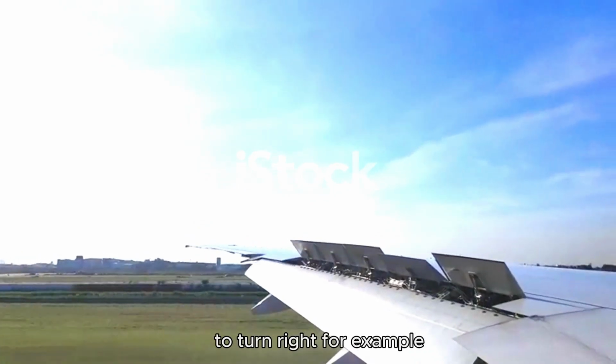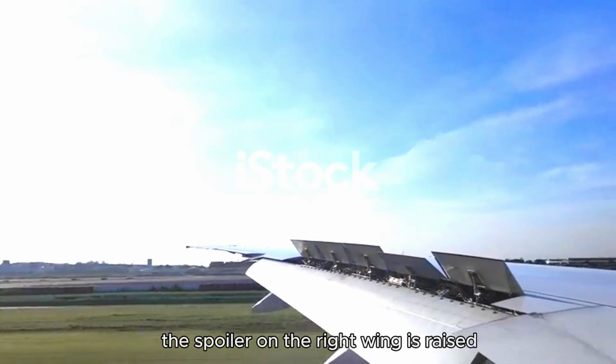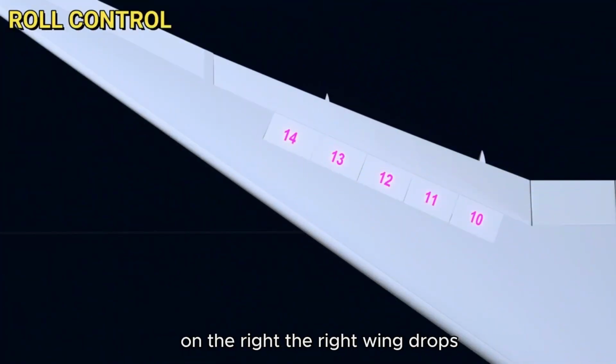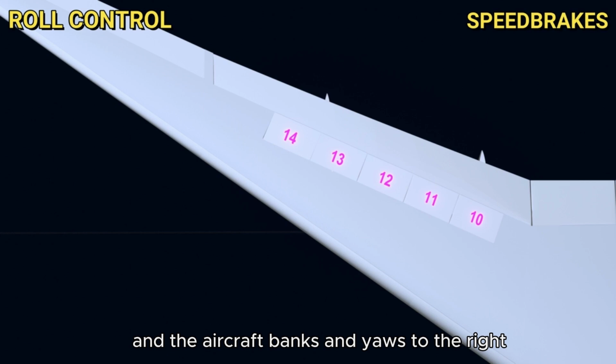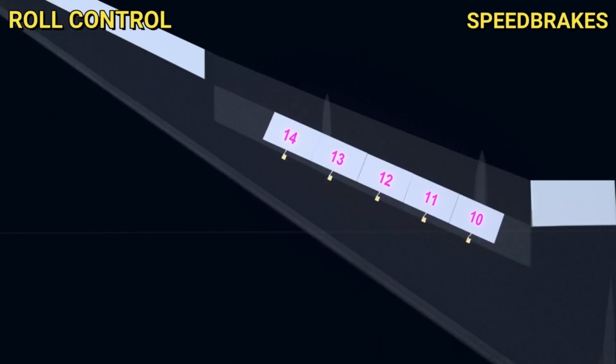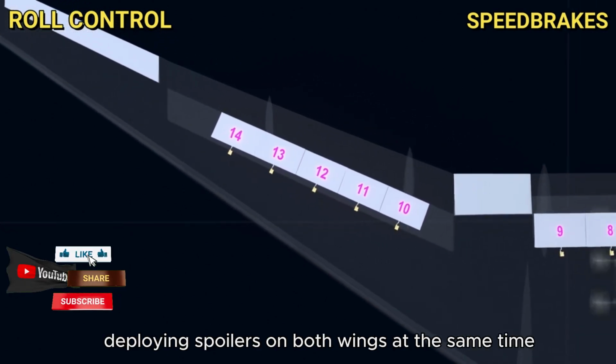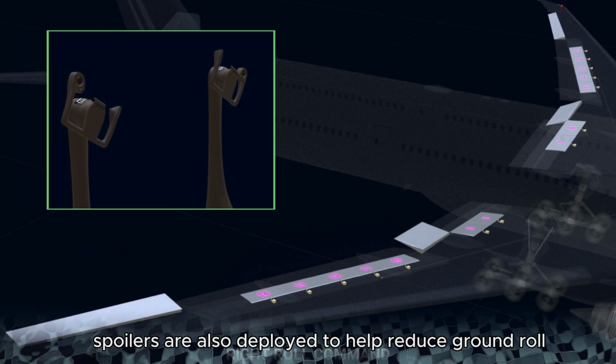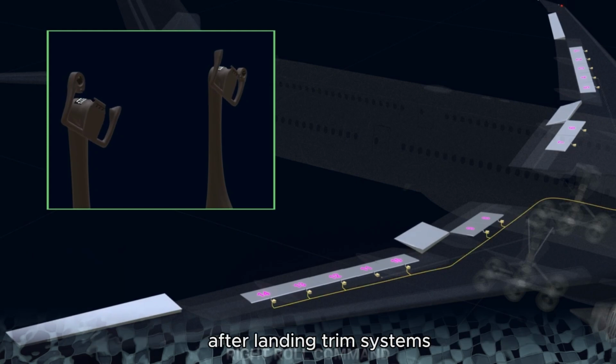On other aircraft, spoilers are often used for roll control, an advantage of which is the elimination of adverse yaw. To turn right, for example, the spoiler on the right wing is raised, destroying some of the lift and creating more drag on the right. The right wing drops, and the aircraft banks and yaws to the right. Deploying spoilers on both wings at the same time allows the aircraft to descend without gaining speed. Spoilers are also deployed to help reduce ground roll after landing.